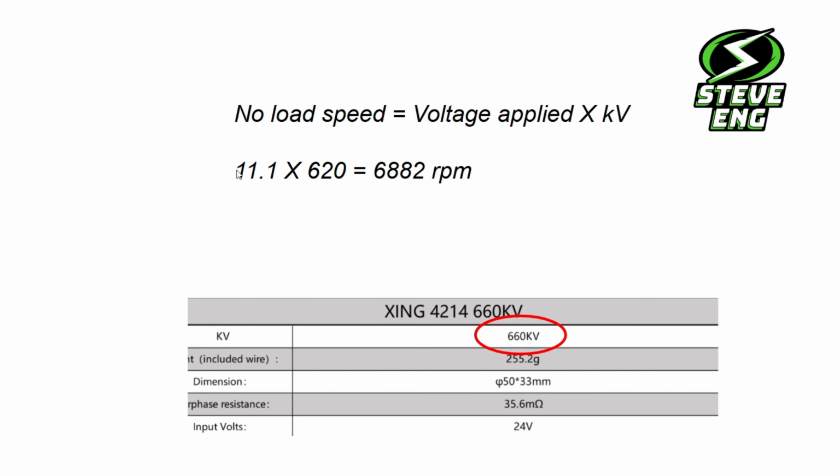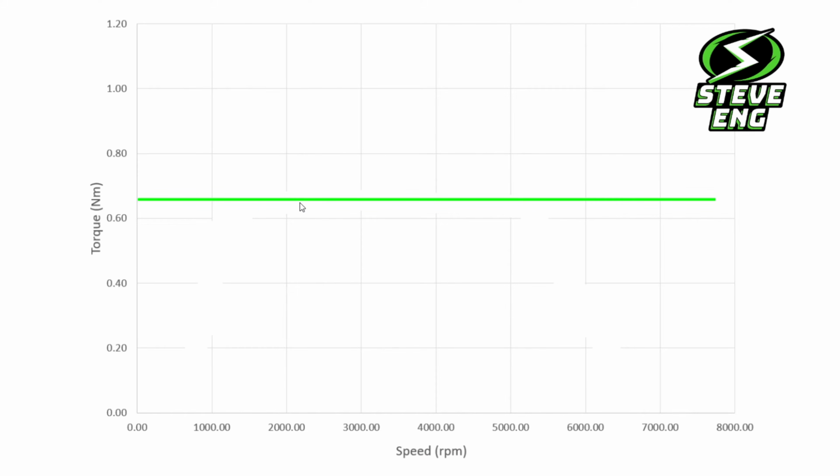It might look like I'm using a low voltage for this, but that's because I did the physical test on a storage charged battery, so I've used the voltage of that battery for that. So what does that give us then? That gives us our point on the x-axis where the torque reduces to 0 and the motor doesn't spin any faster, so I've plotted that there.